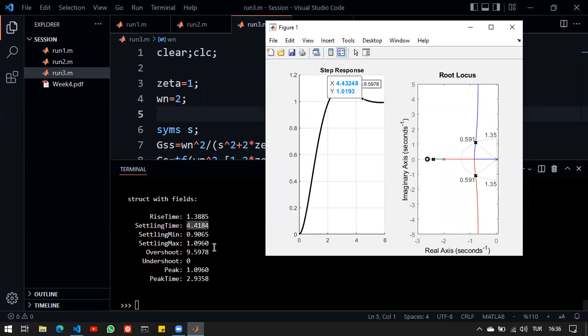So the more dominant the poles are, the better the results will be. Now, of course, we can see that there is a low dominance factor here because we are at -2 something here for the pole at 0, whereas our real value here is, what is it again? Almost equal to 1. So there's not that much dominance factor going on here. But ideally, we want to have a further pole and zero pair here. But for this settling time, it seems like this is not really possible.